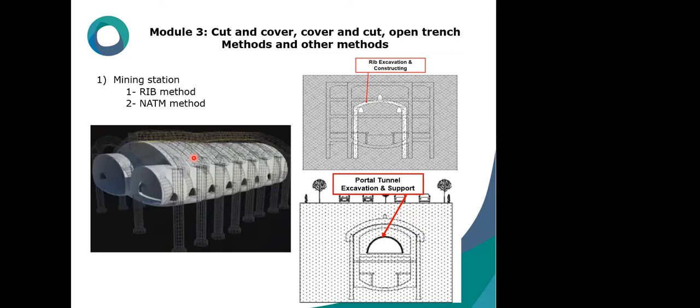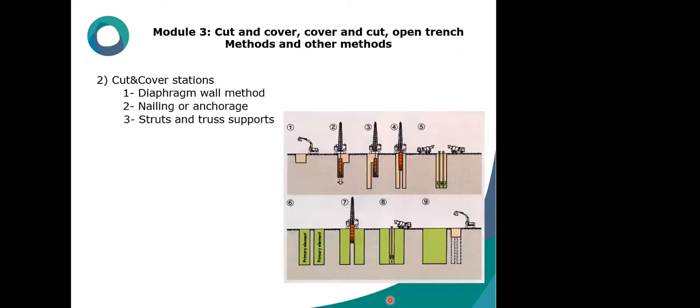They are commonly employed when we have large sections in weak soils, for example, metro stations. Look here, in all these sections, there are piles and beams constructed before the construction of the tunnel started. So the way these elements are constructed will be explained in module 3 in detail. And let's go back to the cut and cover.